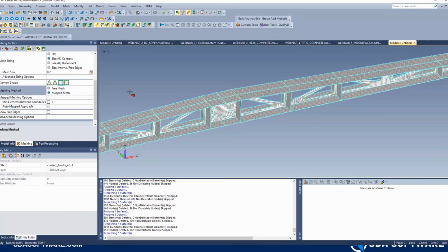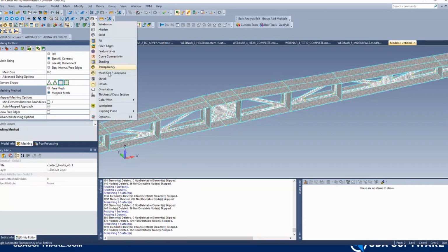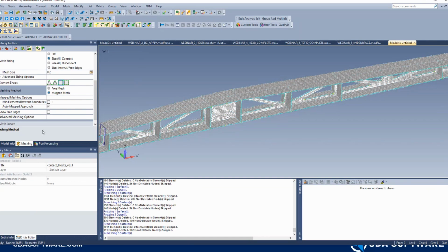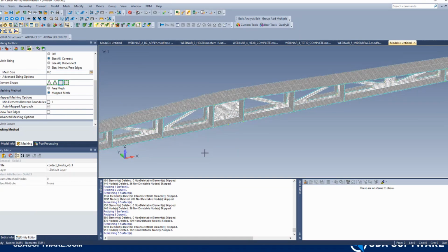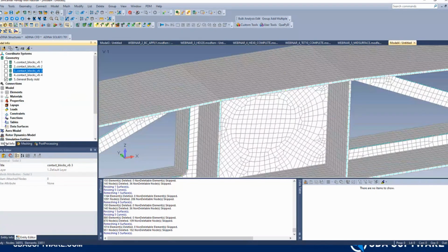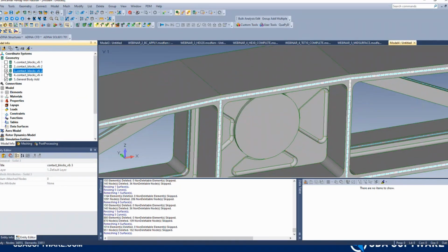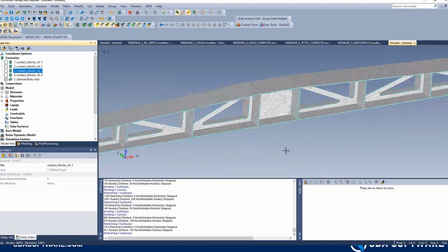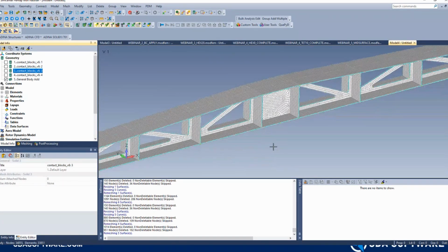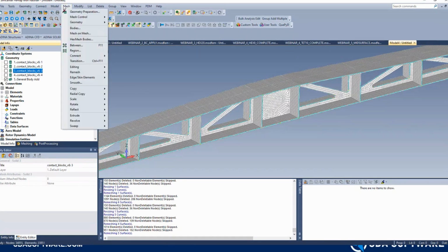Now, one thing we haven't done is, you saw that when I defined the property, I used a thickness of 0.1. So obviously our thickness does not match the original geometry here. Now, in the past, you would create individual properties and assign your thicknesses, probably spend some time measuring. But FEA gives you the ability to automatically resize the elements to the mid-surface.